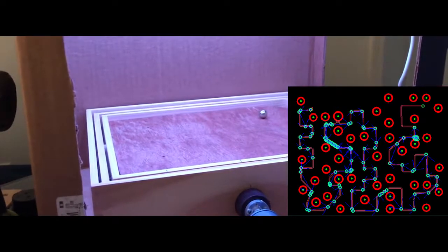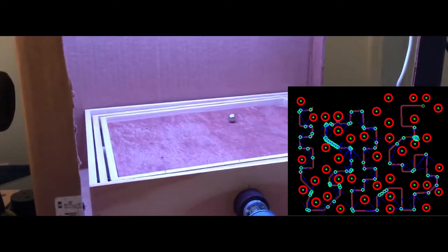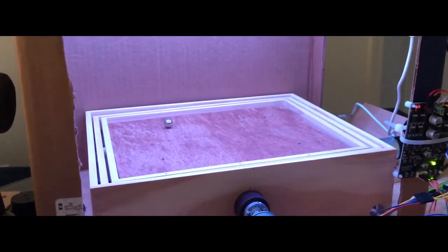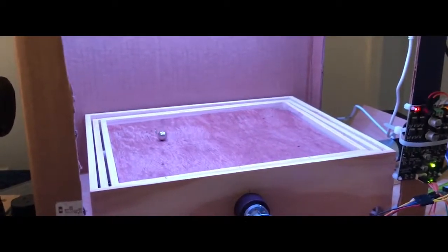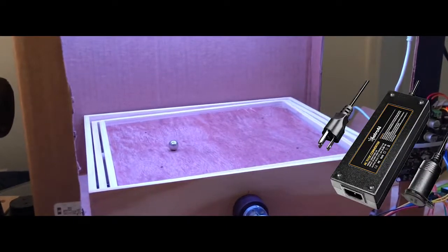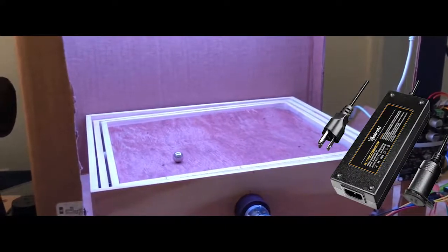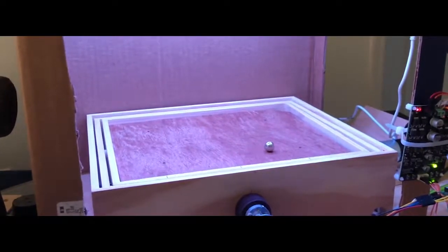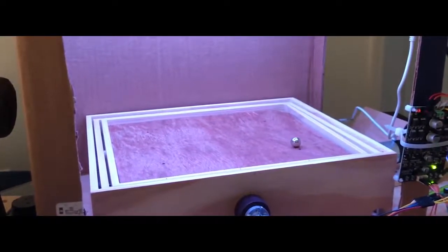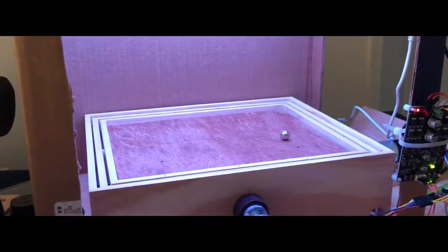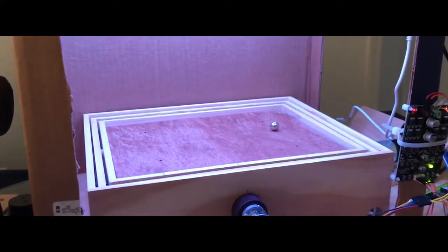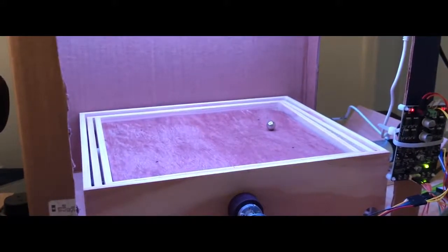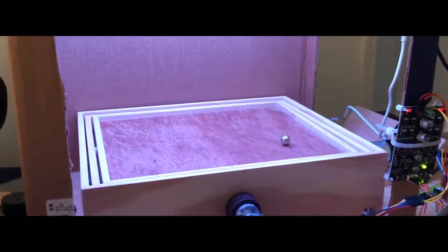Now that we understand the path that we should follow, all the image processing power is now dedicated to updating where the ball is and where we should be going. We have an AC to DC wall adapter that feeds into a dual motor H bridge, then into our two gear motors to power them. The direction and speed of these motors is determined by the microcontroller using PWM signals and digital output signals that are fed into the logical inputs of the H bridge to actually control them.